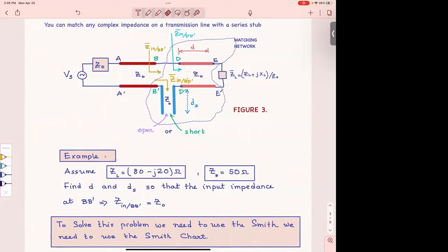So you will need to find a way to connect to the antenna. You're not going to have a stub there in the connection. It's not going to help, it's not going to work for you, it's going to create problems. Usually we try to put stubs inside your network, not at the end of it, not at the load. We try to avoid placing stubs at the load.